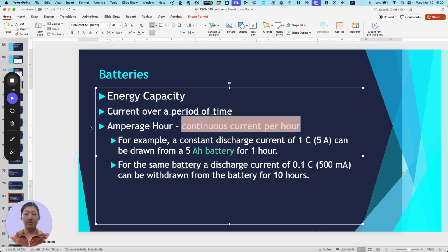If your grommets are not there, you need to insert the yellow spacer. You see, we have our little yellow spacers. And that elevates your board from the carbon plate below. That way you're not physically crushing the components, and you're not going to potentially short anything out. So the yellow spacers go on before you put the board on? Yes, the yellow spacer needs to be on. For most people, it should already be on because we did this last semester. Oh, I see. Mine came out new. Oh, yours came out new. Yeah, they just gave me a bunch of parts.